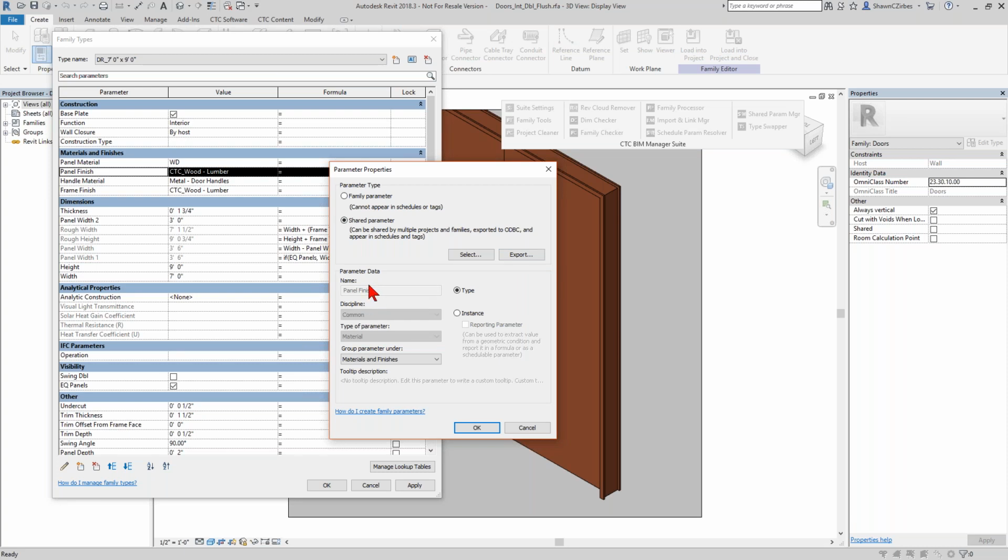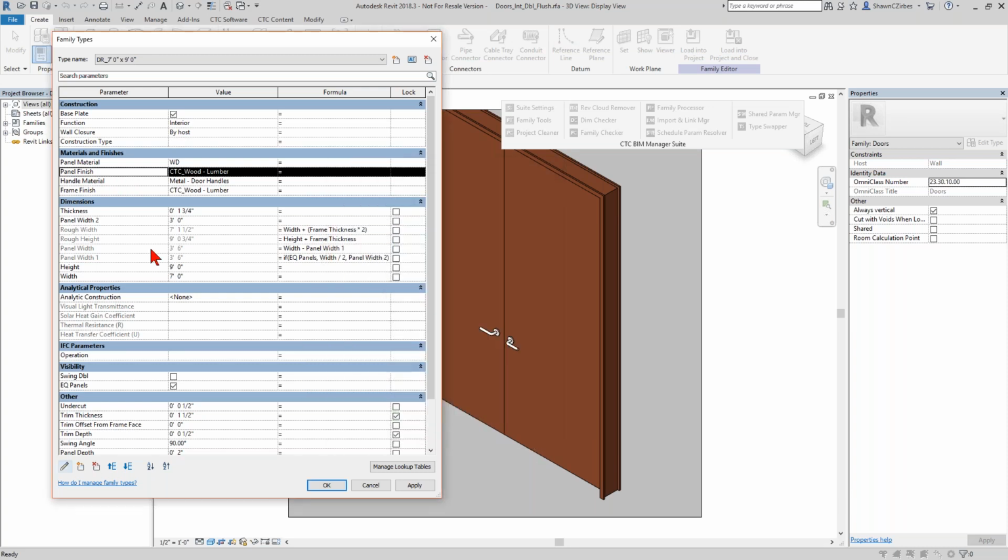So what I'm going to do is use the family processor to set up a rule on how to fix this. And since I know that I've got a number of families with the same problem, I'm also going to have the ability to tell it to run that same exact change across multiple families. Because I could fix this once by hand, but when I've got 10, 20, 30 families with this problem, or more, sometimes thousands of families with a certain problem, and I want to go through and fix all of them, I don't want to do it one by one, clicking edit, going in here and selecting and browsing for some property changes.